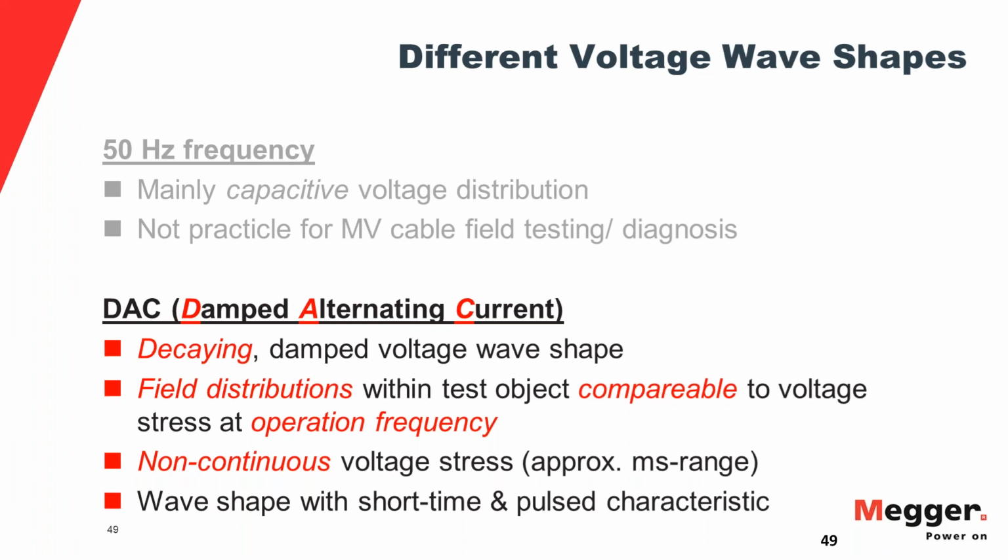size of an 18-wheeler or building size, which is okay for type testing facilities and cable manufacturers because they have a building available. You know, KEMA, the big test lab in Arnhem, they have a whole high voltage lab with huge AC sources when they do these type tests for the 500 kV cables or whatever, because they can afford it. It's stationary, it's not mobile equipment, so you can dedicate a building for that and do it at 50 hertz or whatever, or 60 hertz, and that's fine.